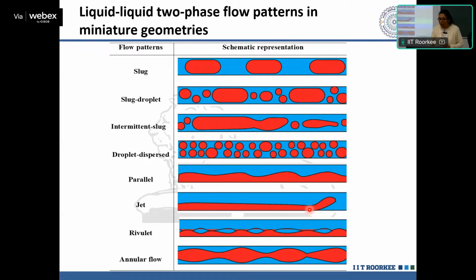In dispersion, sometimes two small drops can join, and sometimes we can see a larger drop. So that is called droplet dispersed flow. There's a mixture kind of flow, a mix of droplets and fine droplets. Actually, the distribution of droplet size, you can say.